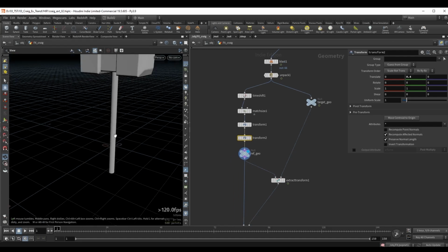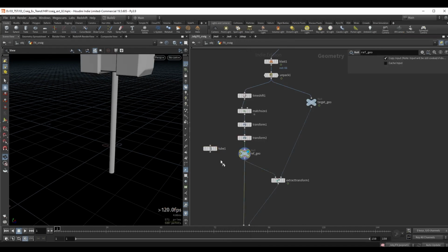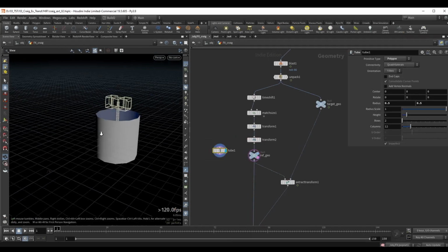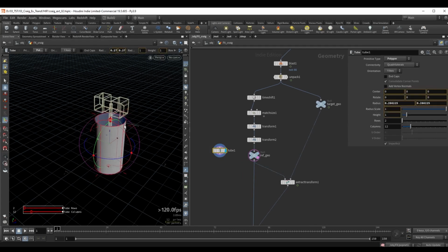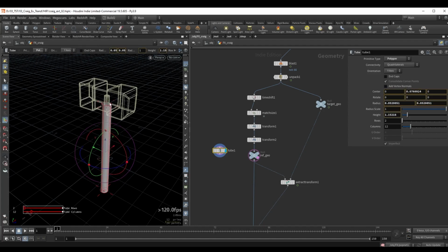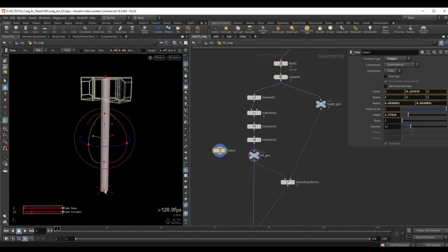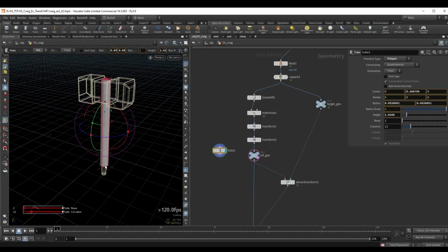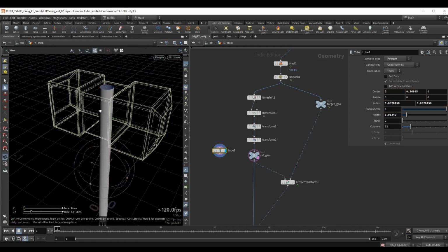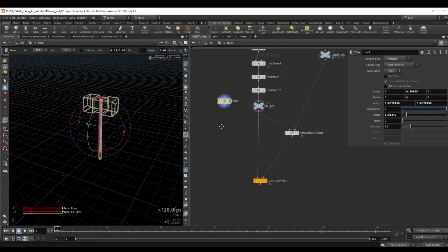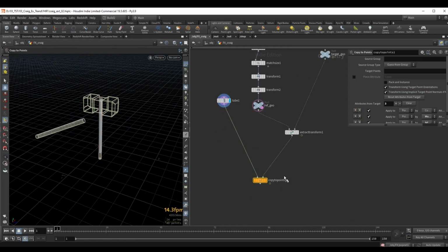Which means that to the side I will do a tube, and let's template our reference geometry and look at our tube. Let's press enter and I will hold down shift and let's scale this in, and I will bring this up slightly and also bring the lower end up and try to match the size of this hammer, and maybe scale this in even more. I can replace now this hammer entirely with this tube geometry, and let's take a look.